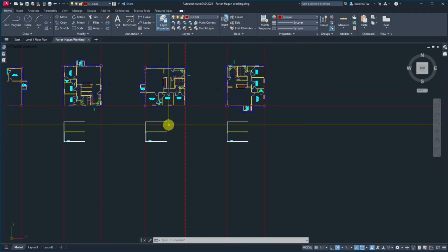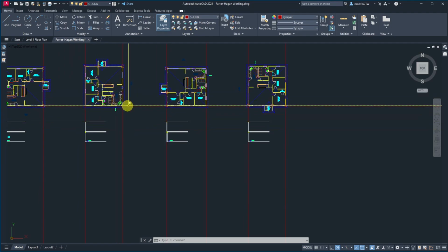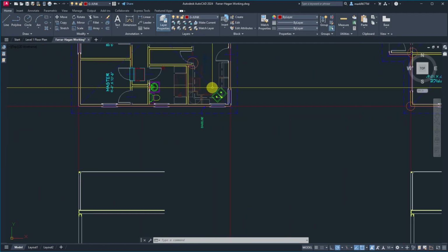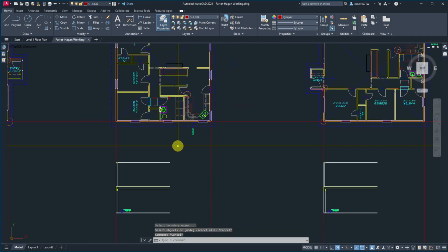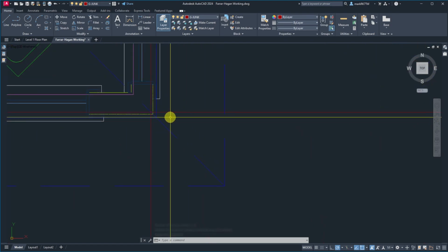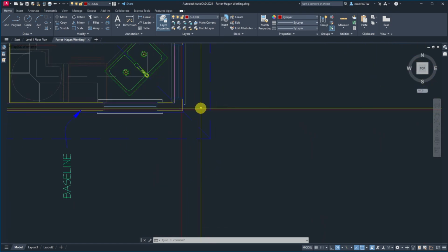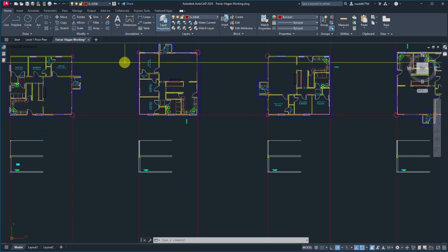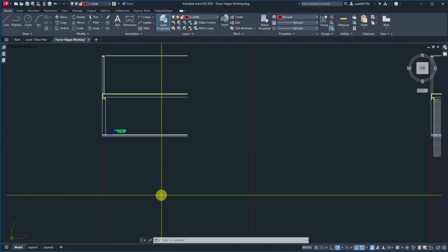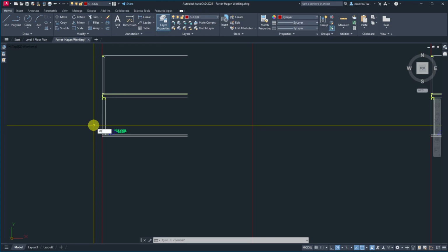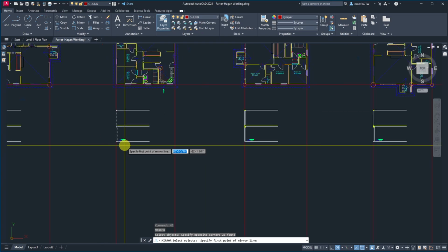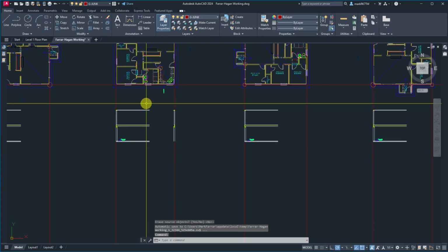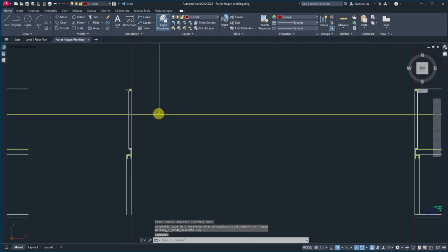But right now, I'm interested in figuring out this roof, and I really want to know this side and this side. So I'm going to extend, well, even this. That distance should be perfect for the roof. You have a brick veneer out here in the front. Well, that's not the front. These are both sides, so that's perfect. So I can mirror this about that roof line, and it should land right on it, and it did.